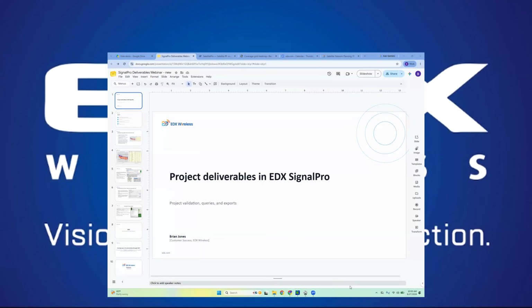So let's talk about first validating the propagation model and assumptions themselves in Signal Pro. And as we go through this, as usual, I'm going to jump into the software here so I can show you what we're talking about. As usual, if I'm starting up a new project or just checking through my project template to look at how things are set up, first I would address my terrain and clutter databases, 3D buildings if I've got them. But then I would want to look at these propagation model options.